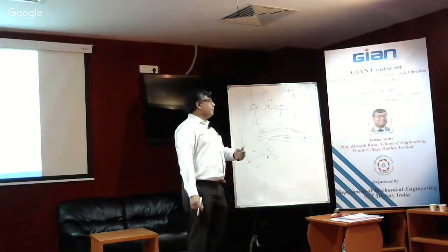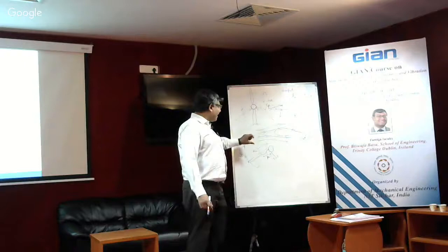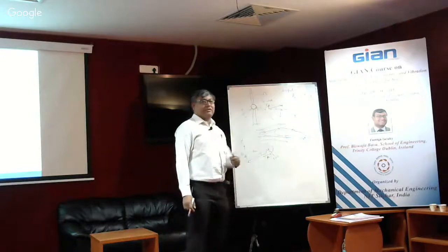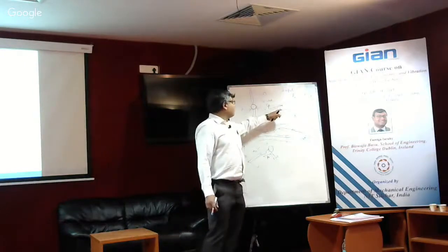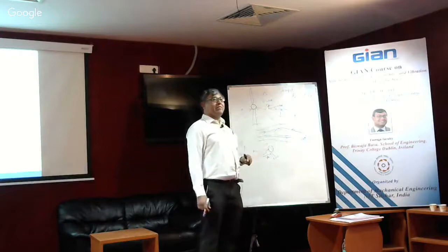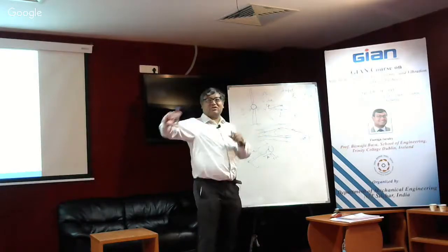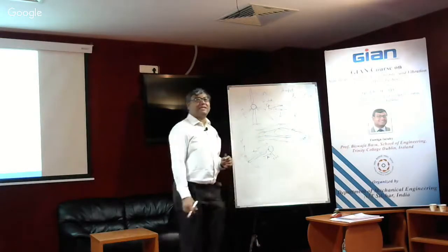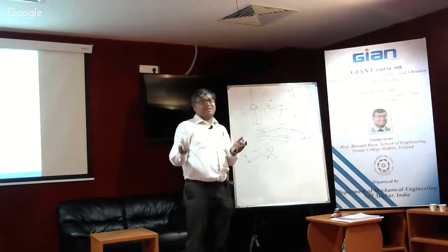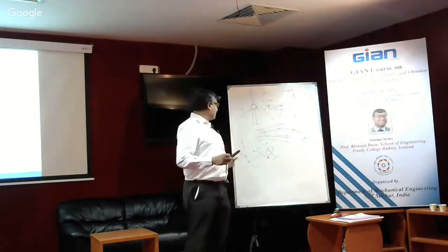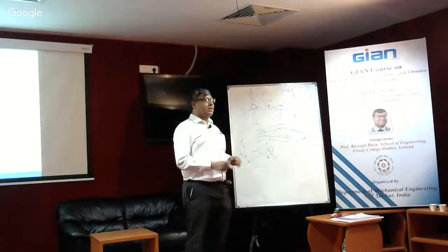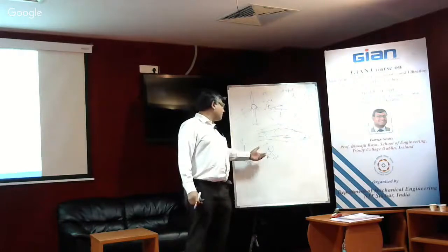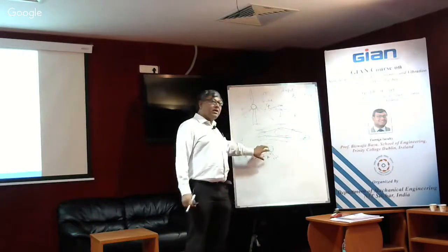But say if we change the angle of the blade itself, so this is my airfoil. At the tip, it's like this. But let me now twist the blade. That's why the blade is given what's called a pre-twist. The blade is not just a straight blade, but to make sure that we still have some angle of attack near the hub, we twist it.